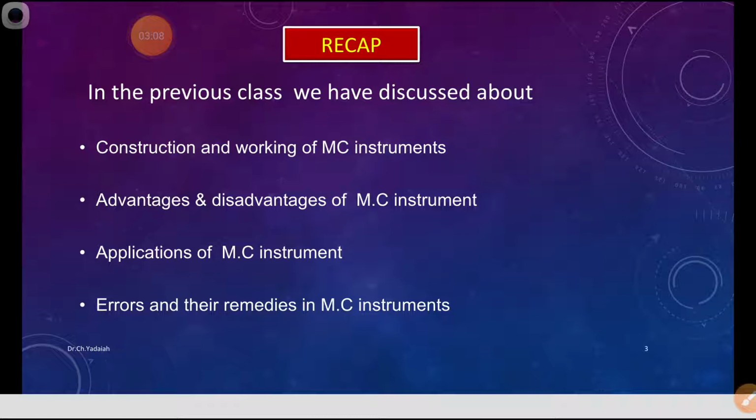The burden on the circuit is very less, but it is limited to being manufactured with a coil of 100 milliamperes only in case of ammeters, and it can be used for measurement of high range with the help of a low resistance material as a shunt.